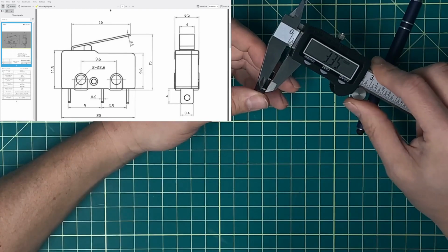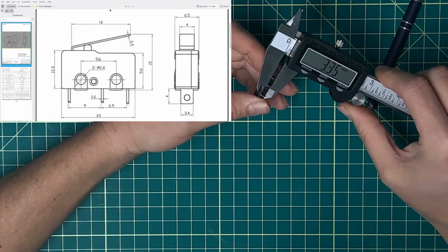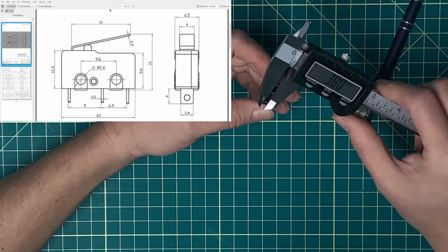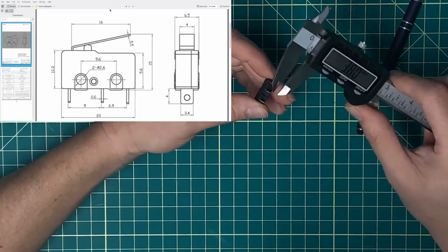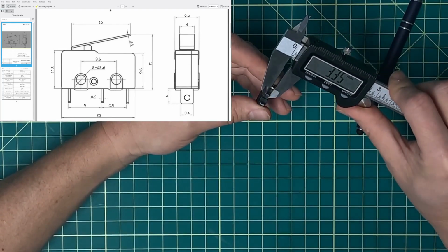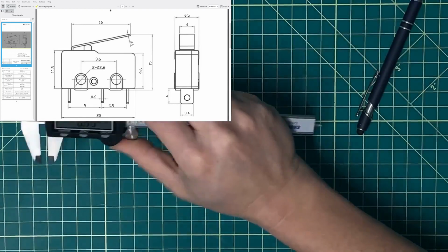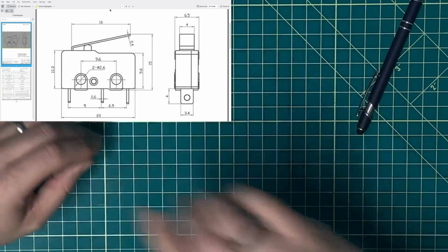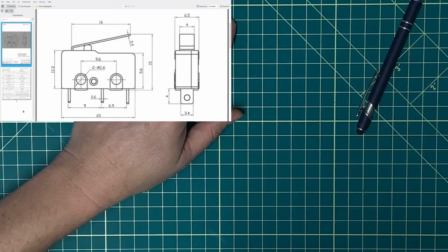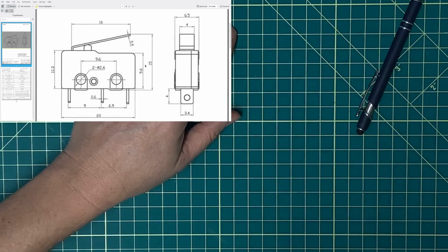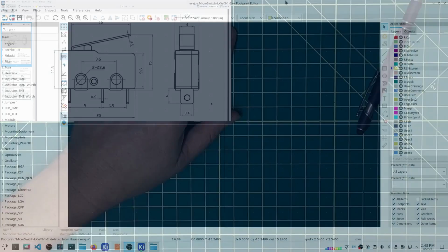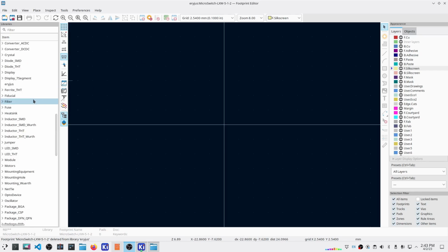That's reasonable as well. I'd rather have it smaller than wider, because if I use these dimensions, I just can fill it with solder, because it'll end up being a plated through hole. With that, I think we can go ahead and use those numbers up there, and let's see if we can make a footprint. Okay, this ought to be fun. Let's see what we can do, because this is the first footprint I've ever made from scratch.